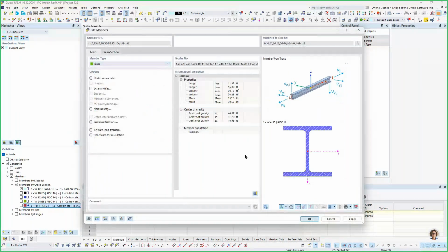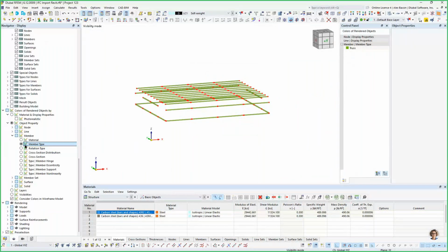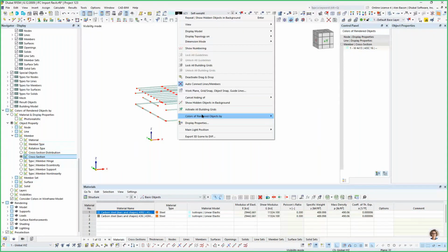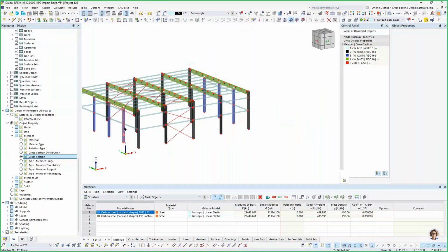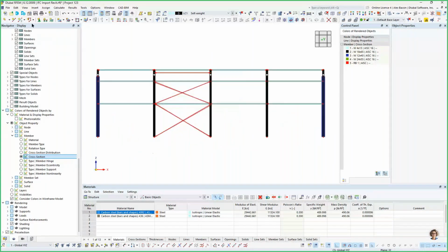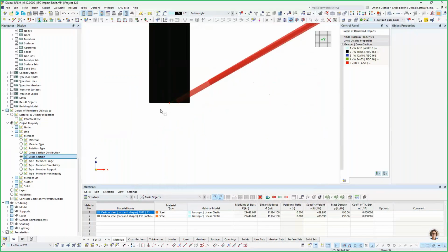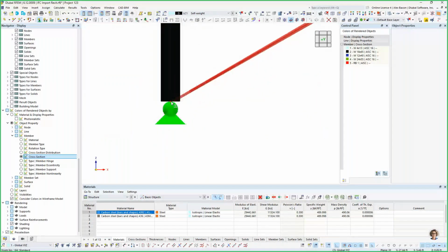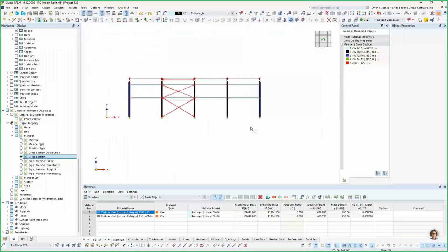And we don't need to add any hinges to our columns in the center because they already have those hinges defined. Yeah, so we have our member types defined. Now we want to add in again our supports. So we'll add in our hinge supports down here. Catch just those nodes at the bottom of the columns, like so.